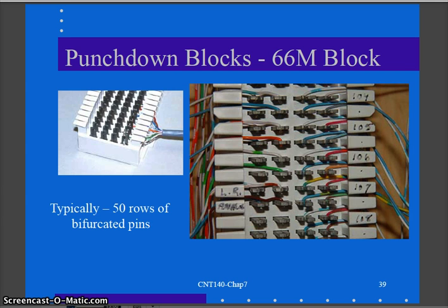That's the way this was set up to do. And here's zooming in, showing the cabling coming in and punching in. This is showing zooming in again, phone cabling. There's your tip and your ring being terminated, and then over here is the other connection. All we would need to do is put a jumper in there to connect the two.